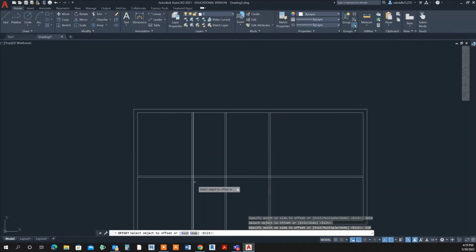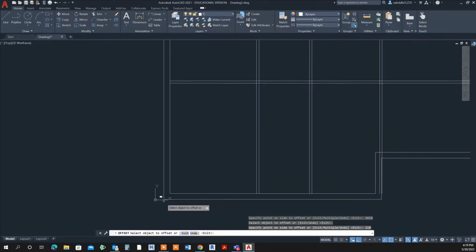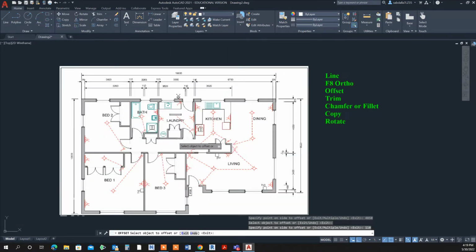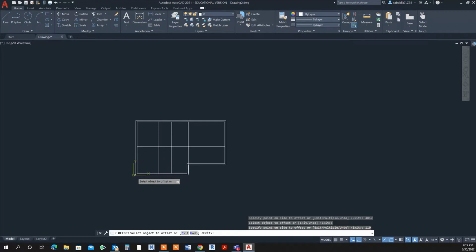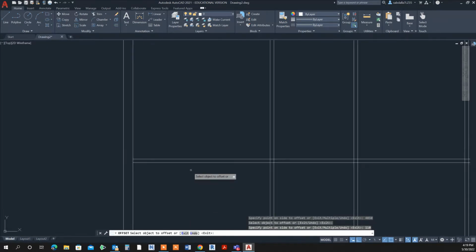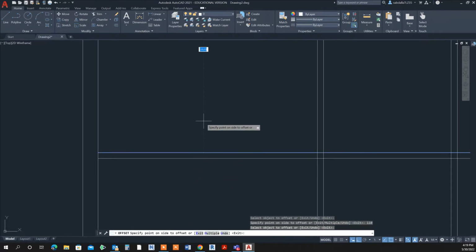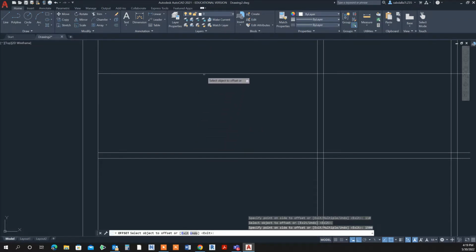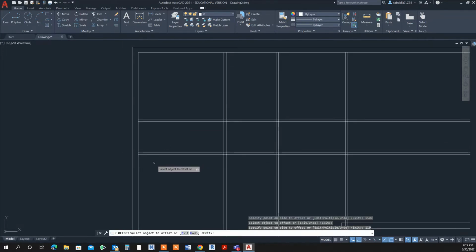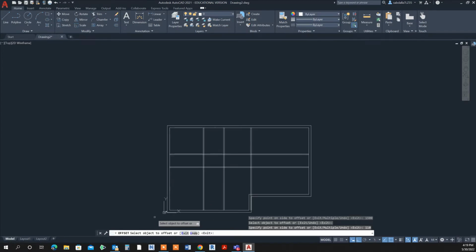Okay, now I have some rooms here, so I'll just look at my plan. I still have this corridor here, which is, I guess, about 1.5 meters. There's no dimension to it, so I'm going to use 1.5 as a corridor. So I will just come up here and use this corridor, 1,500. And the wall thickness is 110. Okay, and then I start cleaning my plan accordingly.